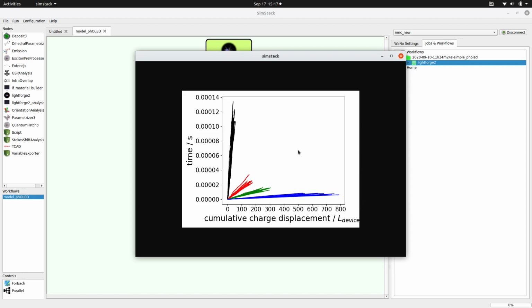They can be very noisy for less ideal systems, but if you cannot do a linear regression through, say, the second half of it, then the current values that are calculated would not be reliable. So this is basically how you can roughly check whether what you simulated was actually in a steady state. On the y-axis it's just the simulation time.